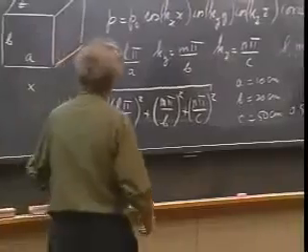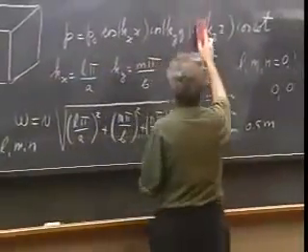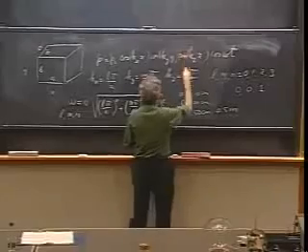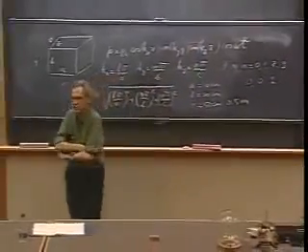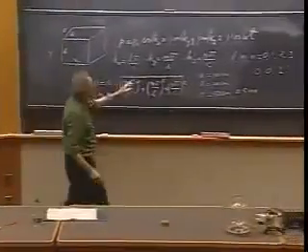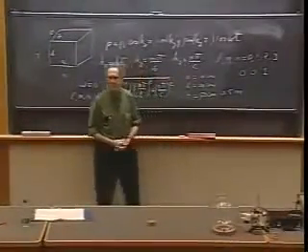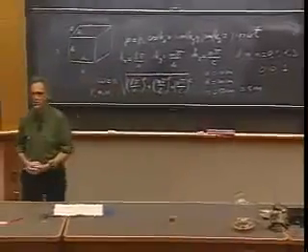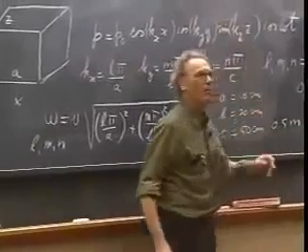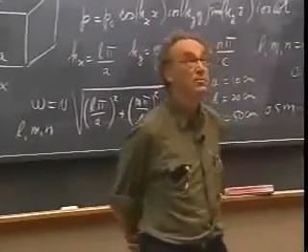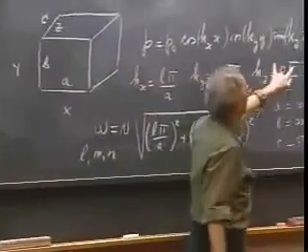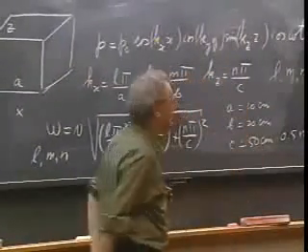Well, that we can easily do. We just change the cosine into a sine. And nothing else changes. Because look, if now I make kz n pi over c, then you will see for any value for n that you choose, this will indeed become a pressure node. You will get 0. And so this now is the right solution then, when the panels in the z direction have been removed.